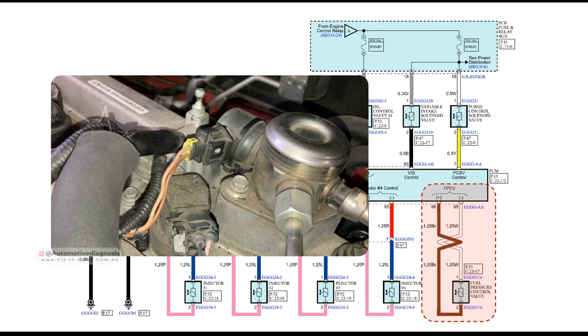So it means if fuel is not regulated properly, if the fuel pump is providing higher pressure, injectors will inject more fuel, which is going to cause a rough engine and bad fuel consumption. If this fuel pressure regulator is regulating the fuel too much and fuel pressure is too low, injectors won't be able to provide enough fuel to the engine, and of course you will have poor acceleration as well.